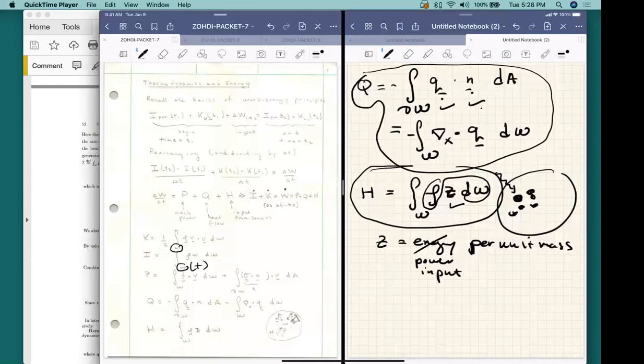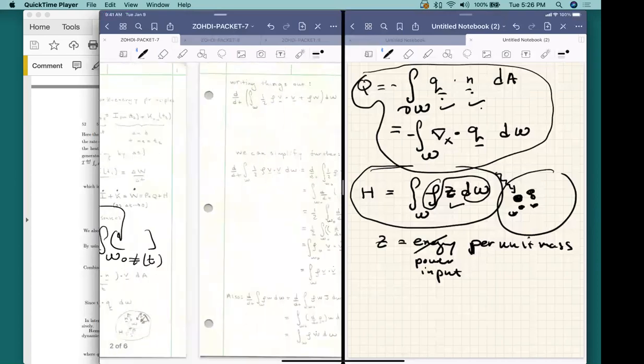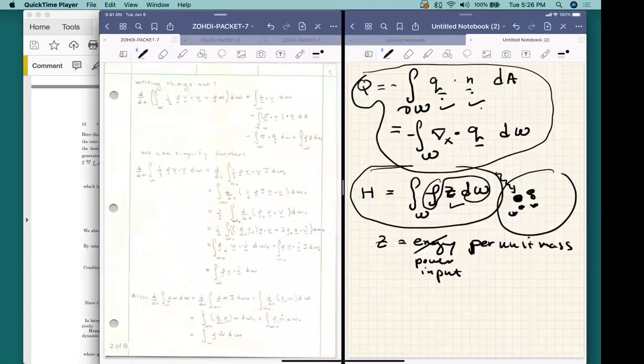of time. So the problem is, if I were to come cavalierly here and take a time derivative of this integral, I would also have to take a time derivative of that boundary integral, which is a big pain. It can be done, but it is not easy. So it is better to convert this into an integral over some reference volume that doesn't change, which is not a function of time, and then bring the derivative inside and take the derivative of all the junk inside. And that's in fact exactly what we do in this term here.